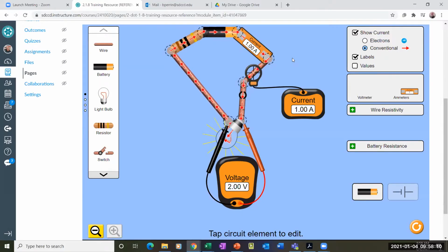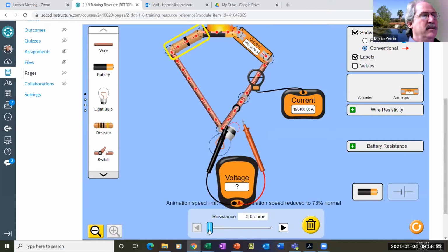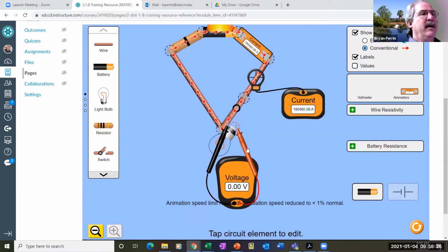Let the factory smoke out. Exactly. The advantage of this is that even if I bypass my load, kick this down to 0. Now I've got a real problem here because you can see I'm going to blow the fuse because the current's so high, but my inductive clamp's just going to say, hey, you're out of your limit.